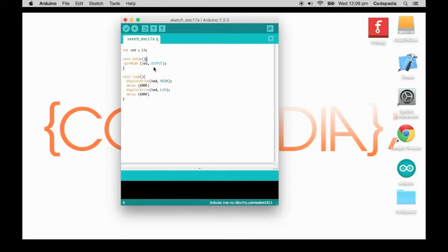At this stage, LED is just a number, but as you can see in void setup, we make LED a pin and an output. So now that we're talking about void setup, this is where you set up different components and parts of the code. And this section of code only runs once in the program, whereas void loop runs over and over again. So here we make LED the variable a pin, and we make it an output.